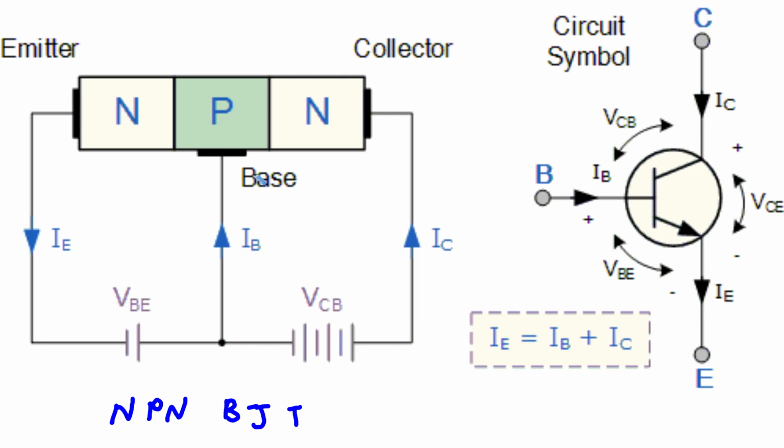For the transistor to work in its most common mode, known as the active region, we must apply specific voltages, a process called biasing. As shown in the diagram, the emitter-base junction is forward biased by the voltage source V_B. This means we apply a positive voltage to the p-type base relative to the n-type emitter, which reduces the natural barrier between them and allows electrons to be easily injected from the emitter into the base. This flow of charge into the base terminal creates the small base current, I_B.